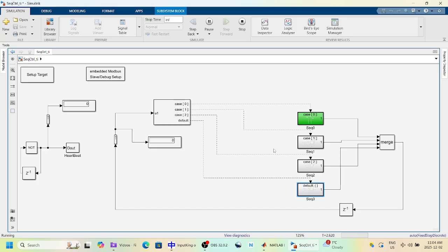Did you notice the heartbeat display block? Even though the LED on the demo board blinks every 0.5 seconds, the display in Simulink might update much more slowly. That's because the state machine runs every 10 milliseconds, and its probes can consume a lot of your PC's CPU time. Meanwhile, the heartbeat block runs every 500 milliseconds, so Simulink may poll it at random intervals.